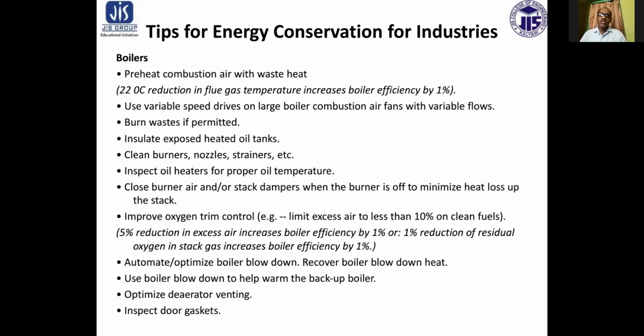Improve oxygen trim control. For example, limit excess air to less than 10% on clean fuels. Automate or optimize boiler blowdown, recover boiler blowdown heat.